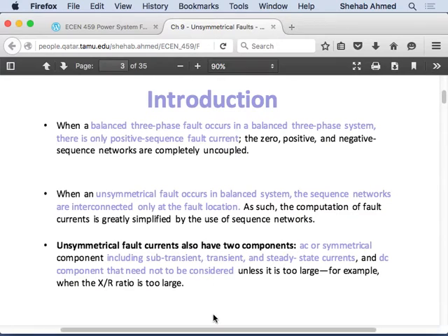If I interconnect them somehow, do you know how to solve it by hand? Let's say I connected them in series, for example, the way we just did. Then find the equivalent impedance, and then divide the voltage by the impedance that it sees. It's exactly like solving a single phase equivalent circuit. It becomes a simple thing to solve. You don't have to do all the loop currents in the three-phase systems anymore, right? So how do you do that?